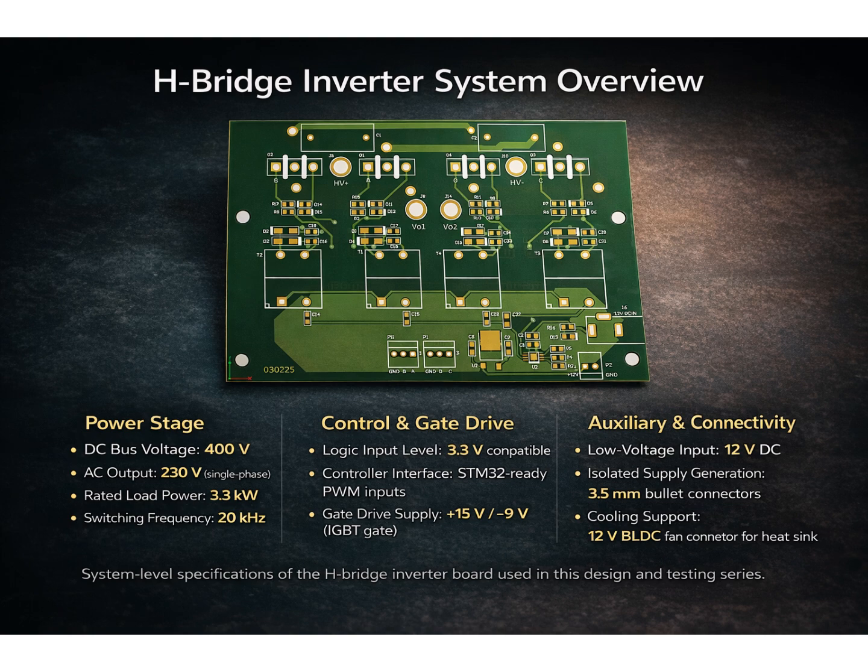Thermal management is also an integral part of the system design. A dedicated connector is provided to power a 12-volt BLDC cooling fan, which is mounted on the heatsink to maintain safe operating temperatures under high-load conditions. This system-level architecture forms the foundation of the inverter design. In the upcoming sections, we will break down each block, starting from schematic design, moving through PCB layout, and finally validating the design through full-power hardware testing.